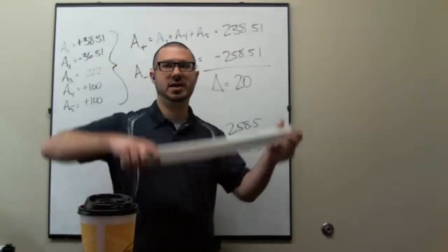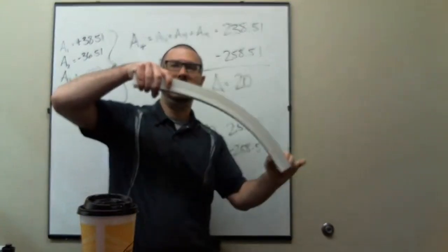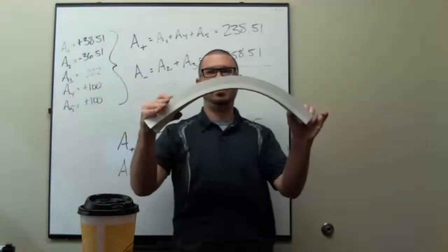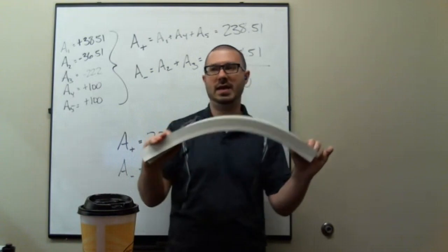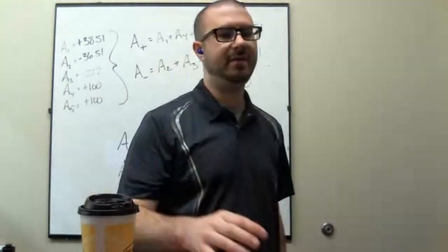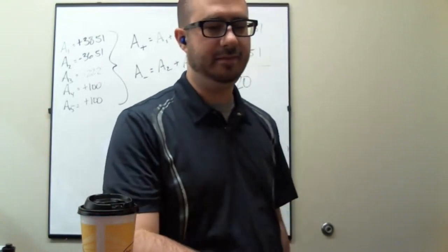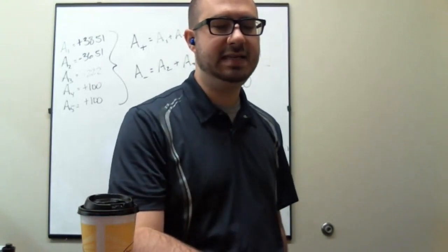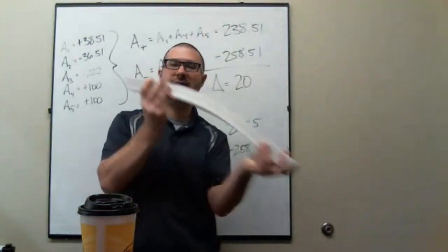But for the sake of discussion here, I think we could probably all agree that it's bending downward, okay? And if you turn that around, it kind of looks like a frowny face, doesn't it? Kind of looks like the beam is frowning at you. Whenever you have a moment diagram that is negative, that corresponds to the beam's deformation being down in nature.